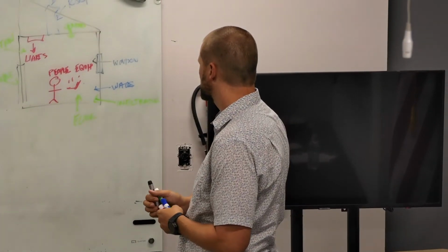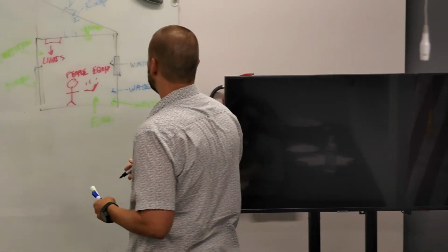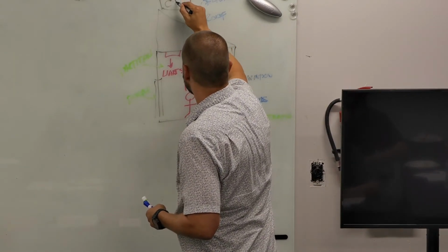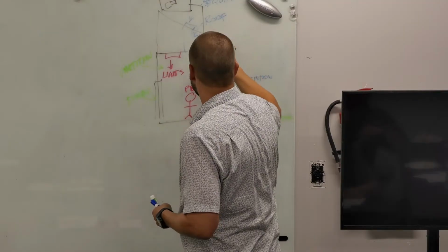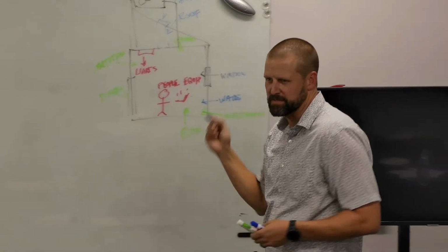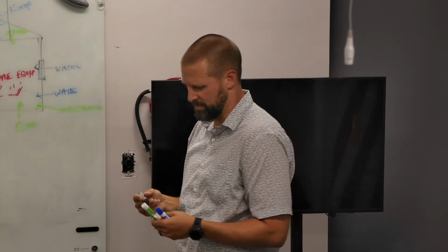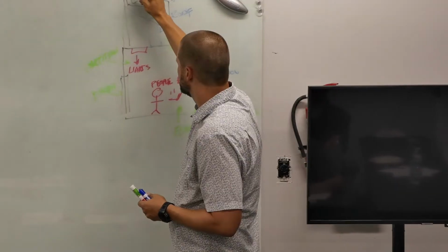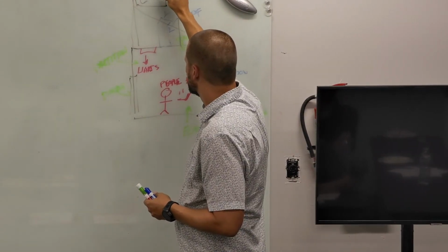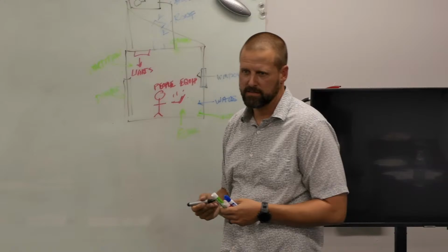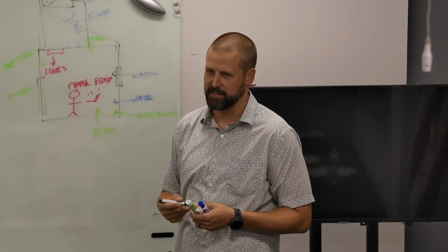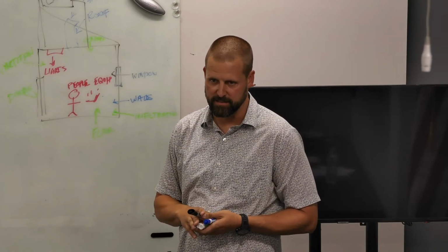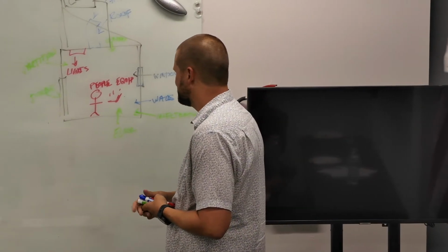Anything else? We're going to overly simplify this, because we're going to get to it more next week, but there's parts of the system that need to be accounted for in the load. The biggest of which is outside air, typically, but fan heat, reheat, duct leakage, that type of stuff.